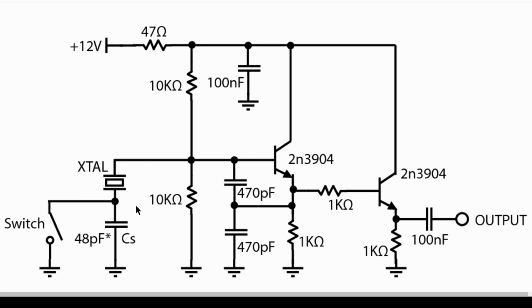In his method of calculating the motional properties of a crystal, with the capacitor in and out of the circuit, the variation will be based on the motional parameters of this crystal. So you can actually calculate your parameters by looking at the difference, plugging in the formulas. Then you get into the formulas for doing this. I'll bring those up and we'll take a look at them.